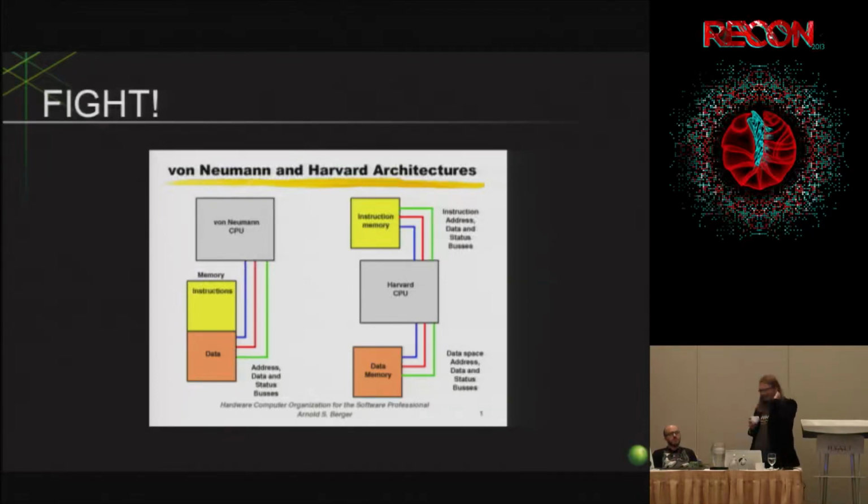Things switch around. The first headache you're going to see is that you have not one bus, you have two buses, because your code and data are physically stored in different places. When you look at the opcodes, they usually only go to one place. It depends on the architecture a bit, and Harvard is a looser term than it probably used to be.